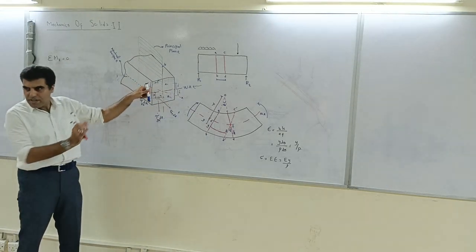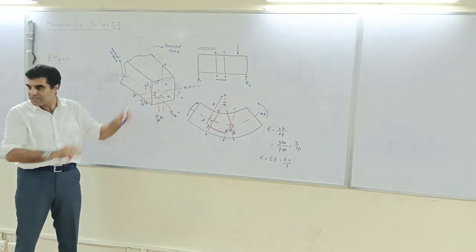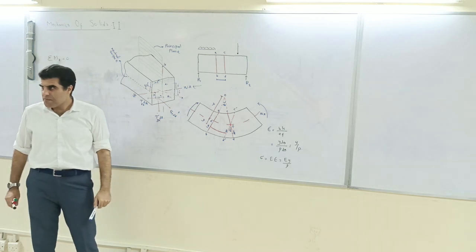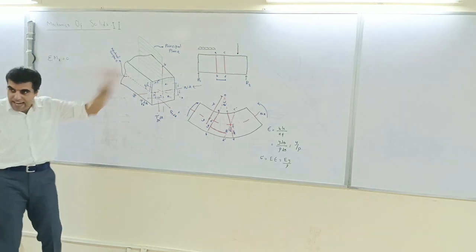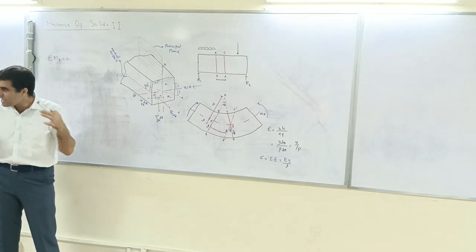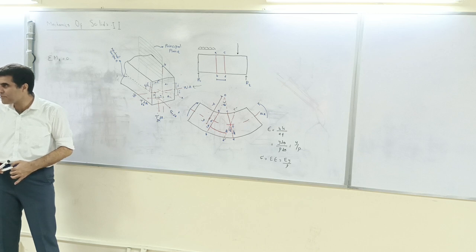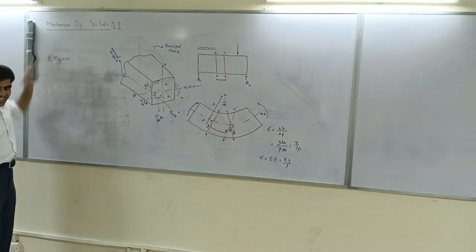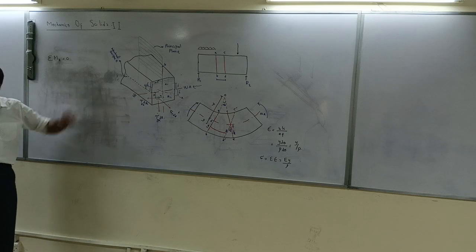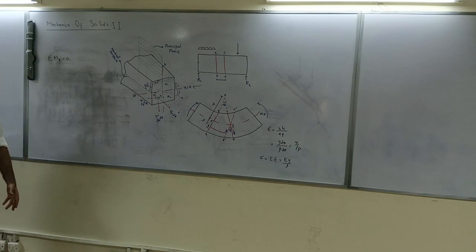When you bend the beam, there is always an internal moment, isn't it? Yes. That internal moment is actually the flexure moment. The moment in the Z direction is the flexure moment. You draw bending moment and shear force diagrams. Those bending moment diagrams are the flexure moments, aren't they? So we have moment in the Z direction, just like the shear in the Y direction. We had a shear in the Y direction, and these shears cause moments in the Z direction.